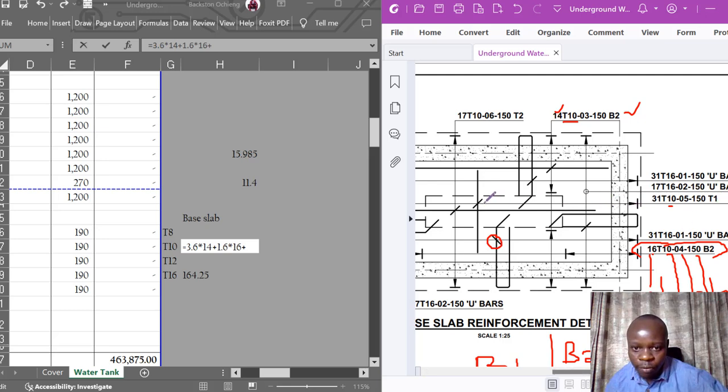Follow the arrow until you find the point where there is a dark line, a thicker line than the arrow itself, perpendicular to it, and in many cases there is a mark or a dot, depending on the mode of annotation that the engineer has adopted.